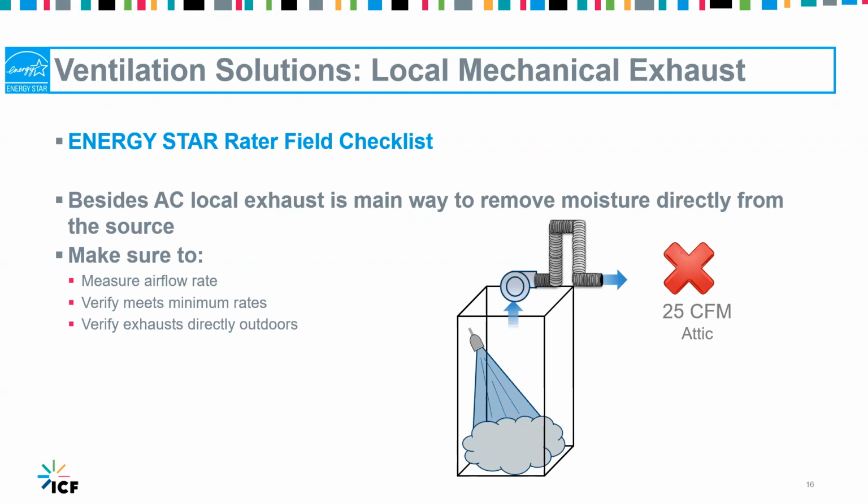From the perspective of the bathroom, if you're standing in the shower looking up, those two scenarios are going to look like the same bath fan, unless someone actually measures that it's pulling enough air and verifies that the air is actually getting outdoors. So that's an important thing. Just having a bath fan isn't enough. You've got to make sure that it's working properly.